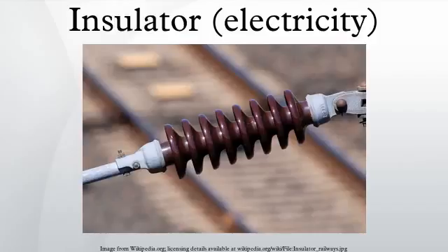In order to make defective units obvious, glass units are designed with Class B construction, so that an overvoltage causes a puncture arc through the glass instead of a flashover. The glass is heat-treated so it shatters, making the damaged unit visible. However, the mechanical strength of the unit is unchanged, so the insulator string stays together.